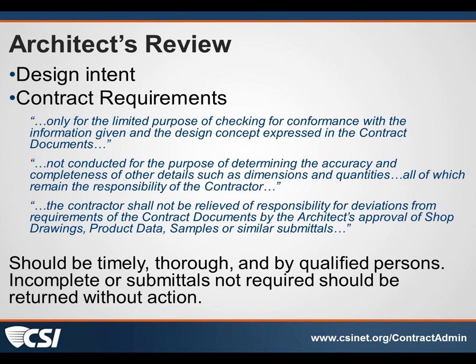So our review should be timely, it should be thorough, and it should be done by qualified persons. Make sure we've got somebody that knows what they're doing looking at the shop drawings and submittals. And incomplete submittals should be returned without action. If you get a submittal and stuff is missing, return it, and return it quickly.